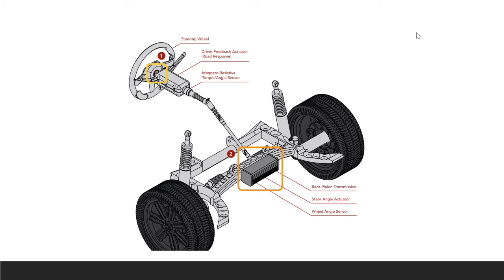Each and every sensor provides data, for example the speed sensor, steering angle sensor, and torque sensor. Every individual sensor will contribute data to the ECU. When the steering is applied, the data from the steering sensor and the speed sensor will be received by the ECU. After receiving, the ECU calculates the amount of steering that is supposed to be applied so that it can assist the driver for smooth steering control.